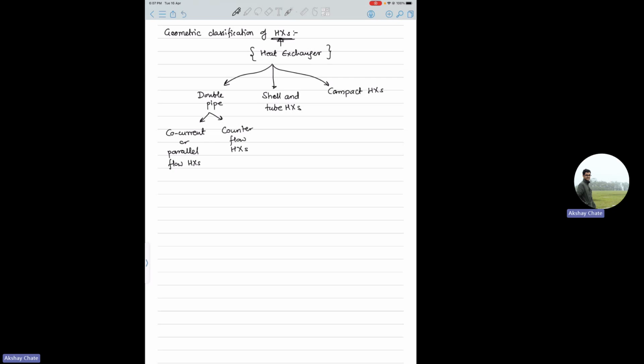So over a period of time, when you use the same water in a loop, or add some makeup water, there will be some deposition of dissolved salts onto the heat exchanger tubes or surfaces, and over time that leads to scale formation and rust formation, and that adds thermal resistance in your heat transfer processes. That is signified by the fouling factor.